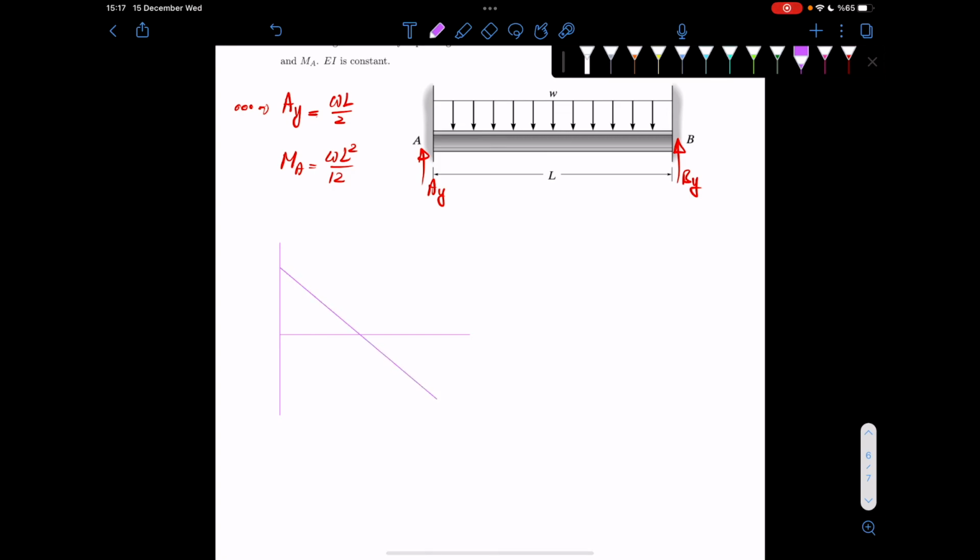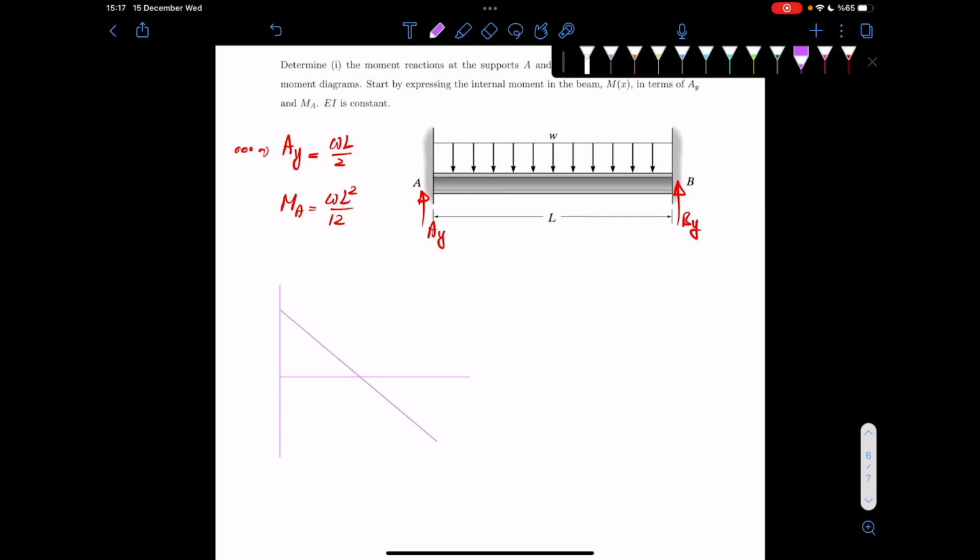This is one of those examples where starting from the graphical approach pays off really highly, because if you think of the moment and so on, maybe it's complicated. Again, it's statically indeterminate. You need to be careful. But if you look at the shear force diagram, it's so simple.